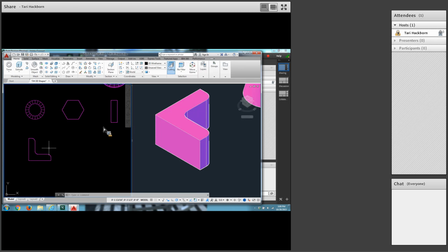For this outline, they have you pick an approximate location, which is right next to the other outline. So I will need my line command. Click, pull upward and type 7/8, and then 7/8 to the right. Okay, now you have to do some figuring. You know that you're going to go 1/4 of an inch down and 1/4 of an inch to the left.